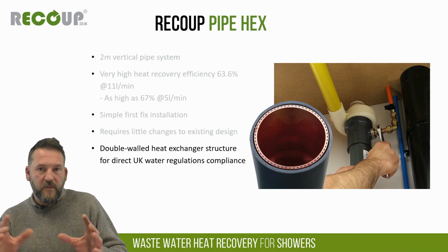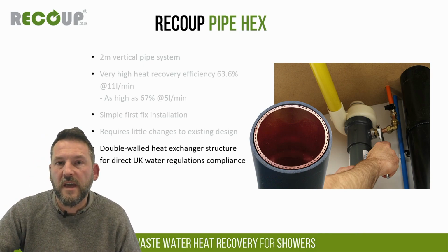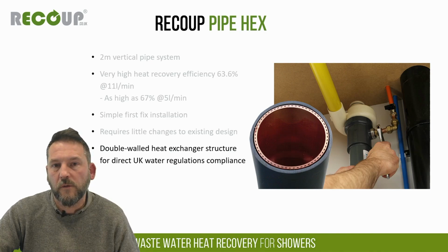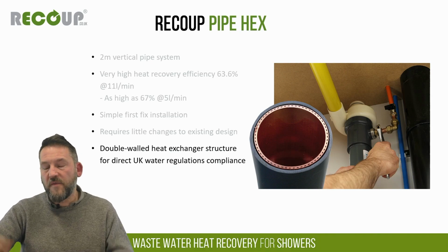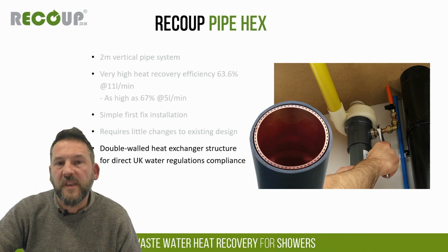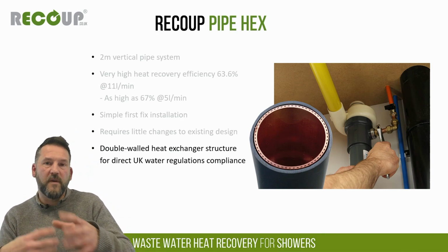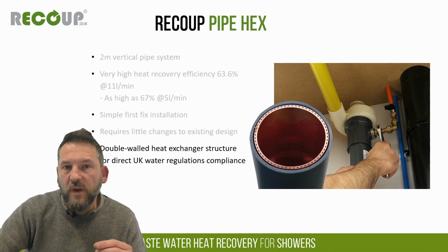Just to give you a cut through on the heat exchanger pipe itself. So what you can see here is this is the copper heat exchanger pipe. It's a smooth internal 50 millimeter diameter heat exchanger on the inside. So this is where the waste flows, and that literally just flows down the middle, clinging to the sides there. And then the cold water main comes between the exchanger and the PVC outer here, and that's where that picks up, turbulates and picks up all that heat energy. The eagle-eyed again amongst you will see that we have striations here, so marks within the pipe.